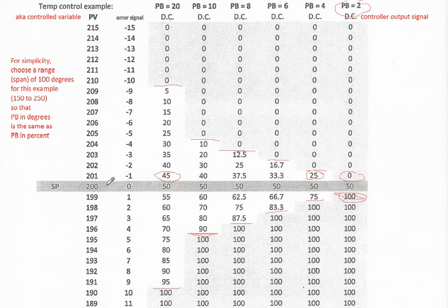Of course, you can see what happens if things try to go over temperature, like we mentioned before. Then the controller output's decreasing. For each degree that you're over temp, it'll cut back 5%. And that's all for a proportional band of 20. Or you could also call that a gain of 5, right?